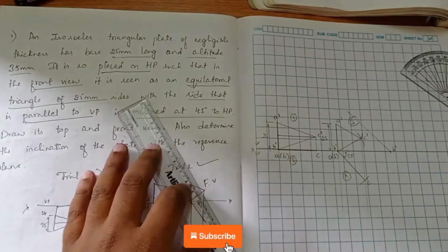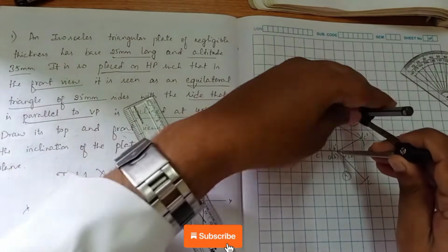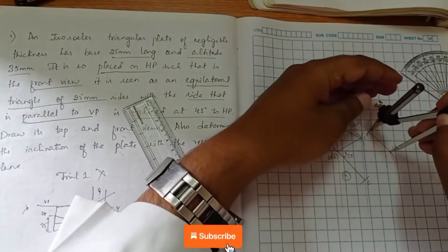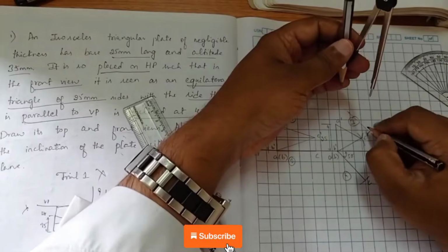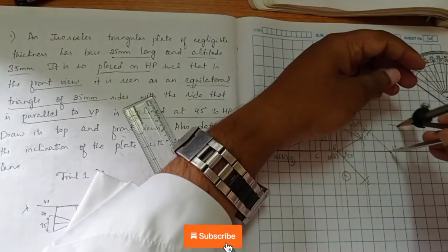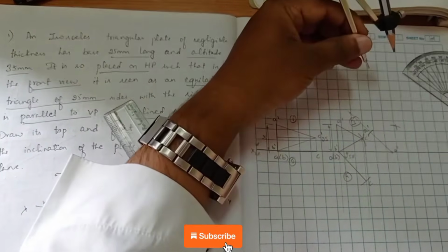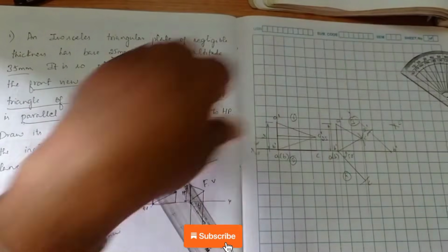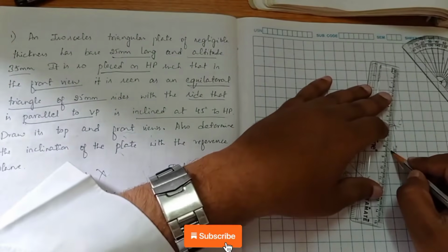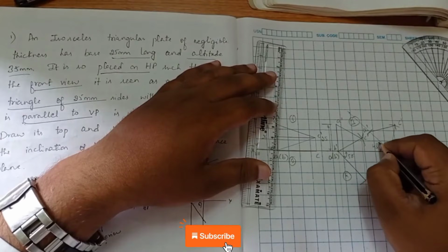Drawing a line. Now measuring this end, because the end A dash B dash is parallel to VP, I'm going to cut the arc. So this is A dash. Now similarly, with the same length, we have to construct a triangle of the same dimension 25, which is already measured. Now we join this. You can see the angle here, it is 45 degrees.